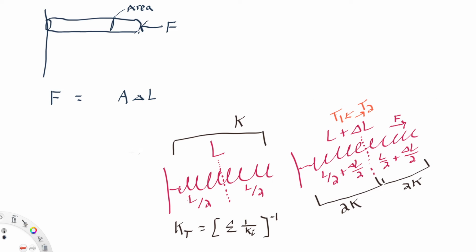So the point of all this is that a longer spring is easier to stretch. Since we are modeling real objects based on the behavior of springs, we expect this to be the same for a rod too. So the longer that the rod is originally, the easier it is to stretch by a fixed amount. So L goes in the denominator because bigger L's means smaller forces required.